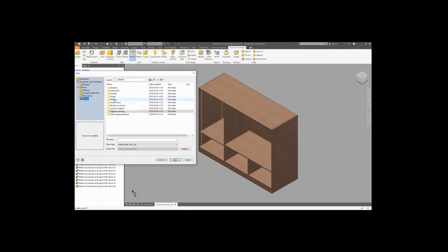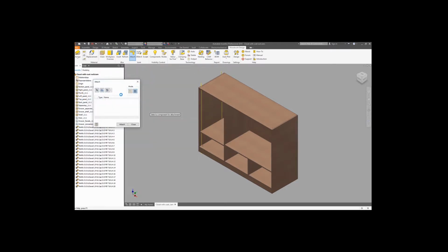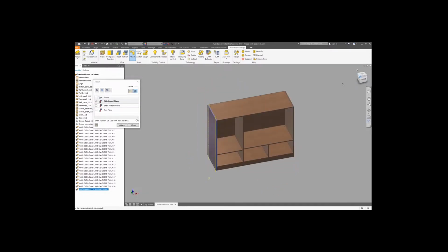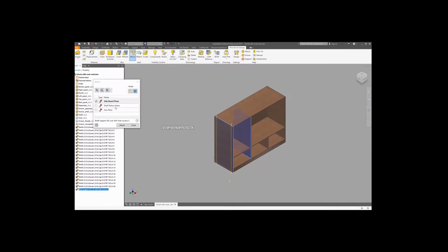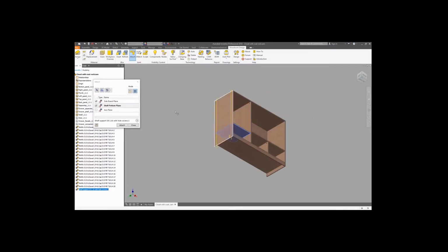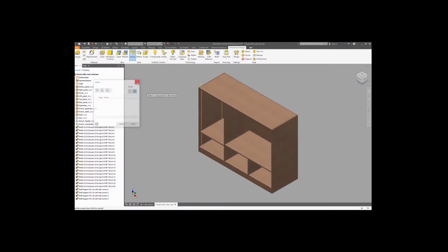So we can browse the library, components, and choose the shelf holders. Again, there are some mounting instructions. So you need to indicate appropriate geometry, the side, the opposite side, the bottom of the shelf, and 2 axes. And that's it. Later we will multiply the amount of shelves.